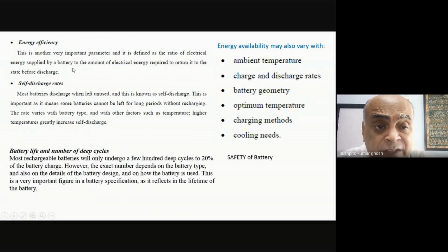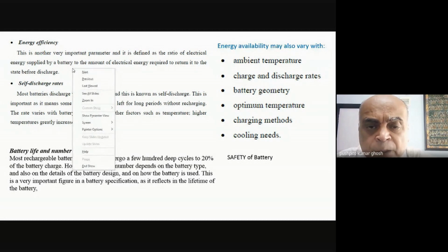Energy efficiency, just that's charge. That's only Coulomb. But actually what you want to know is really the energy efficiency. How much energy did I supply to the battery? Obviously, it will depend on what was the voltage of your battery pack which you used and how much charge actually flowed. Okay, so voltage times ampere times time, the duration, and that is your watt hour. So that's again very important. How much am I getting out of it?